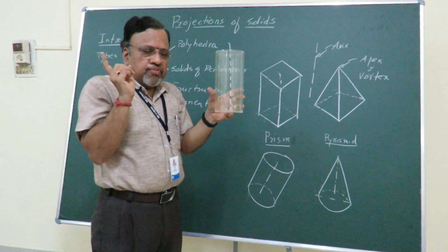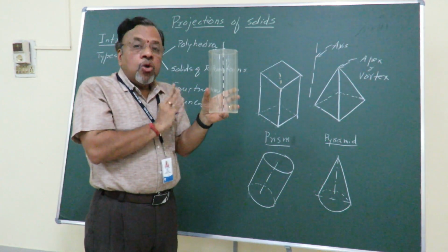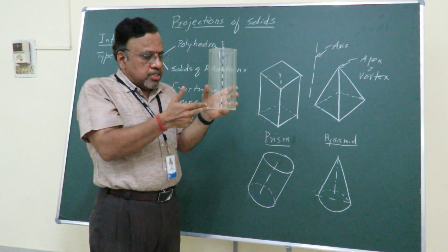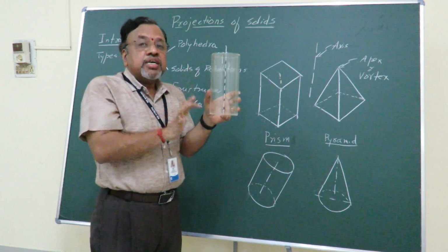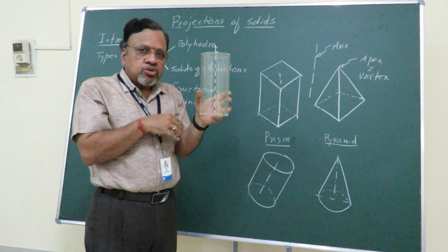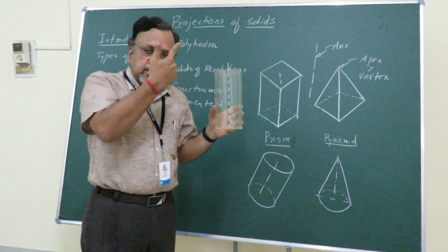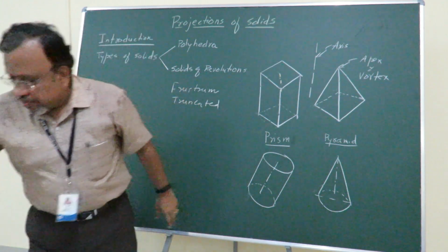Remember, I said we have edges; here there is no question of edges in the case of cylinders and cones. So we have only generators. Since these generators are parallel to the axis, we simply consider them as generators. Whereas in the case of cones, the generators will be inclined to the base, so for cones we consider the generators to be slant generators.